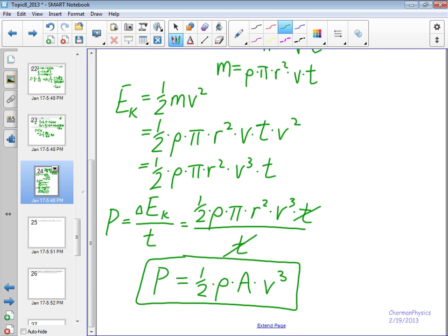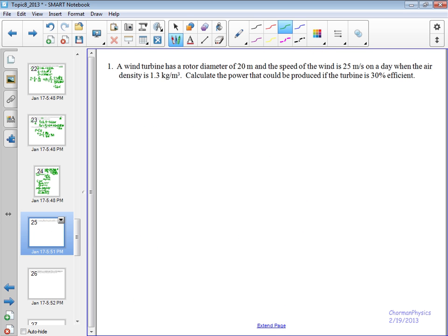So this gives us just the maximum power possibly delivered by the wind, really, is all it's going to tell us, all right? And you also have friction to consider, typical efficiency measures. And then, these turbines, what we do is that we place them separate from each other, okay, so that we don't have turbulence issues, so that the kinetic energy can be captured as much as possible by each turbine. Kind of an optimization thing there, all right?